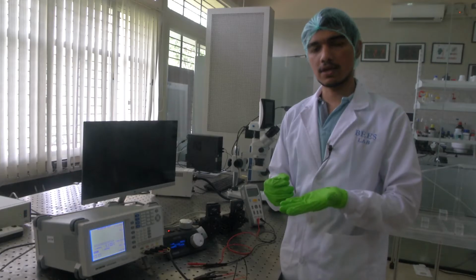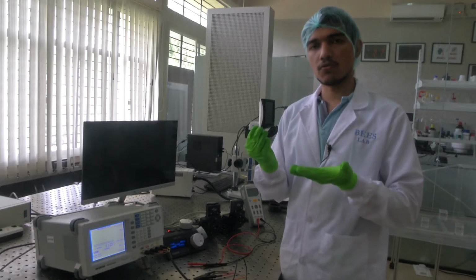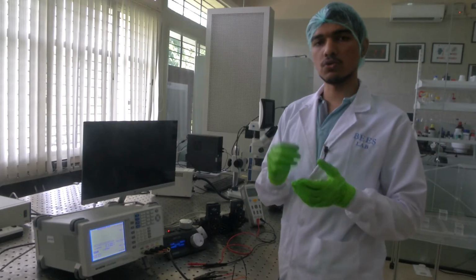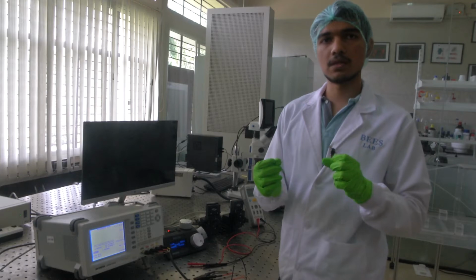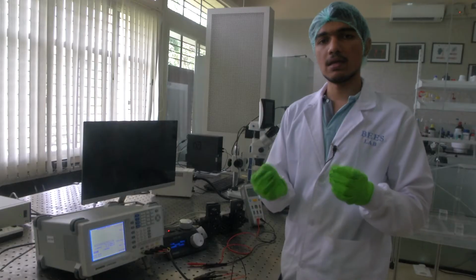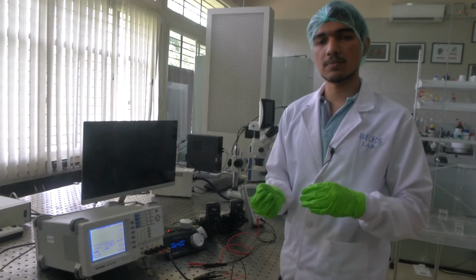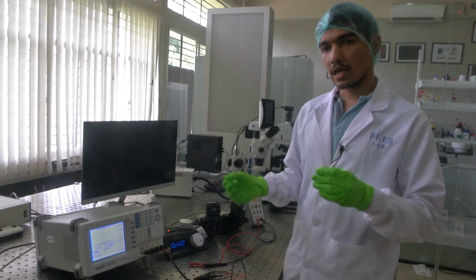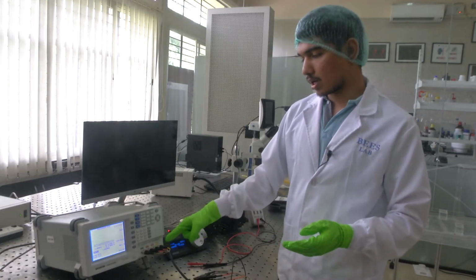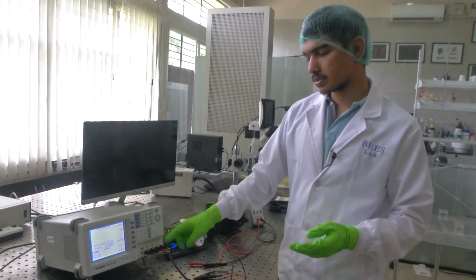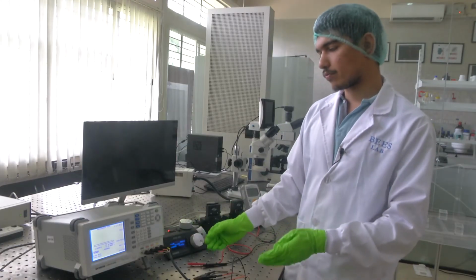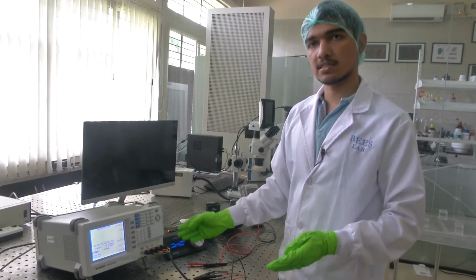In that scenario, when we go for low resistance or low impedance measurement, due to the contact resistance between the probe tips and the device under test, the DUT, there will be a variation in the impedance that we wanted to measure, and there will be loss of accuracy. So, a 4 probe instrument does something different. Of these 4 probes, a pair will be called force probes, and the other will be called sensing probes.